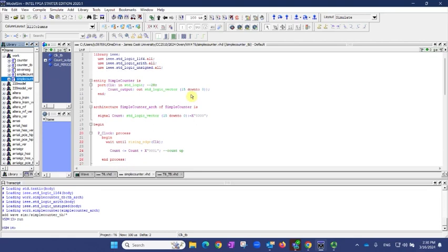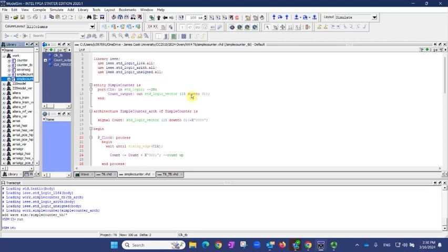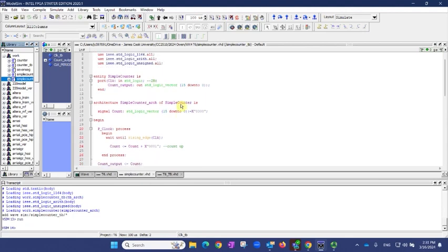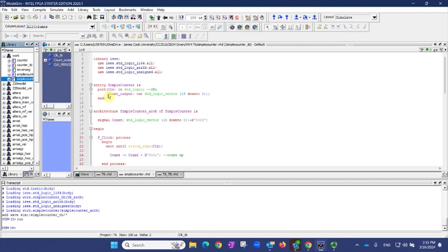Okay, first let's do a very simple one. The whole question asks you to build a counter, counting from 0000 all the way up to FFFF, and by switching a key, you can count backwards. Before we connect with the 7 segments, we just want to create an output called count output. It's 16 bits, where 4 bits drive each 7 segment, so we have 16 bits here.